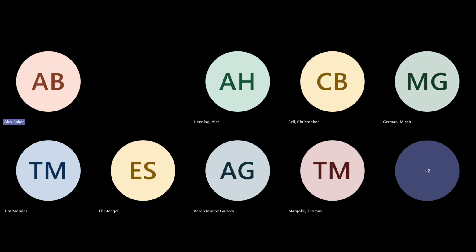Would sink be visualized in the warpage analysis? The answer is yes. If you were to use the deformation tool, you'll be able to see the sink in your warpage. There have reportedly been some issues when exporting the deformed model, where the sink does not appear as pronounced as it does when you deform the model in Moldex3D. So that's something to think about. But in the results themselves, you should be able to see the sink in the warpage results.